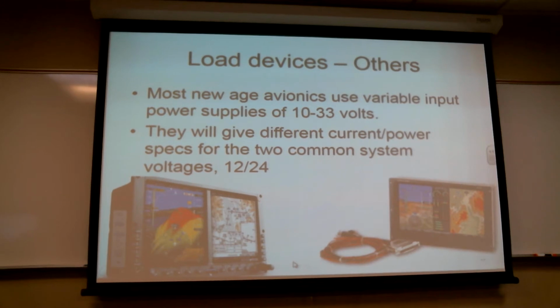From the manufacturer's end of a component, it makes sense to design something that can handle anything from 10 to 33 volts. Now, if you look at an older world thing, like for example, the autopilot out there on the autopilot's test stand. On the back of one of the main modules, there's a little switch on the back side that says like 15 volts and 30 volts.